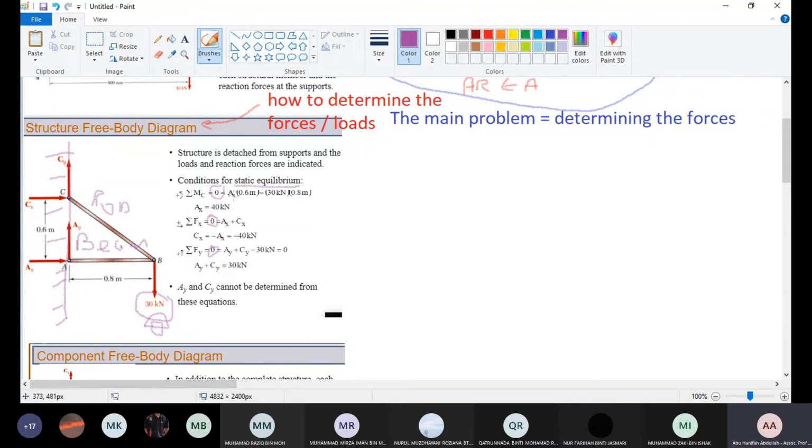So the moment will go to zero. The moment at C, the moment here. Any force acting 90 degrees to C will create a moment. So AX, which is 90 degrees to C, will act on C. So AX times 0.6. It is positive because you have stated that any anti-clockwise moment will be positive. So AX times 0.6 will be acting this way.